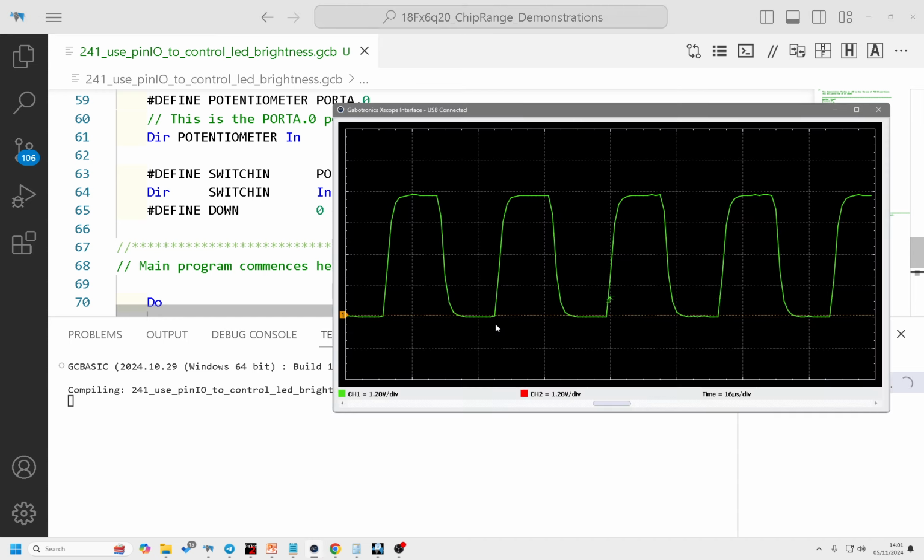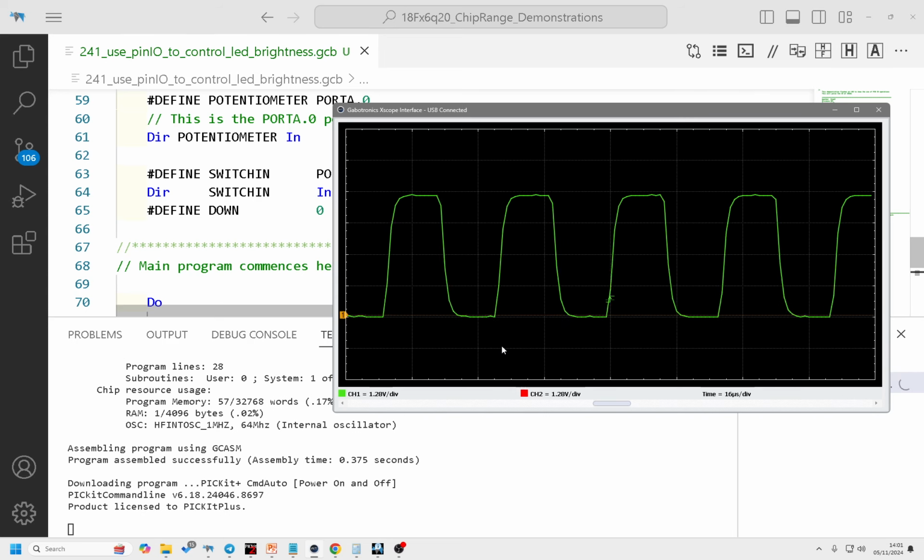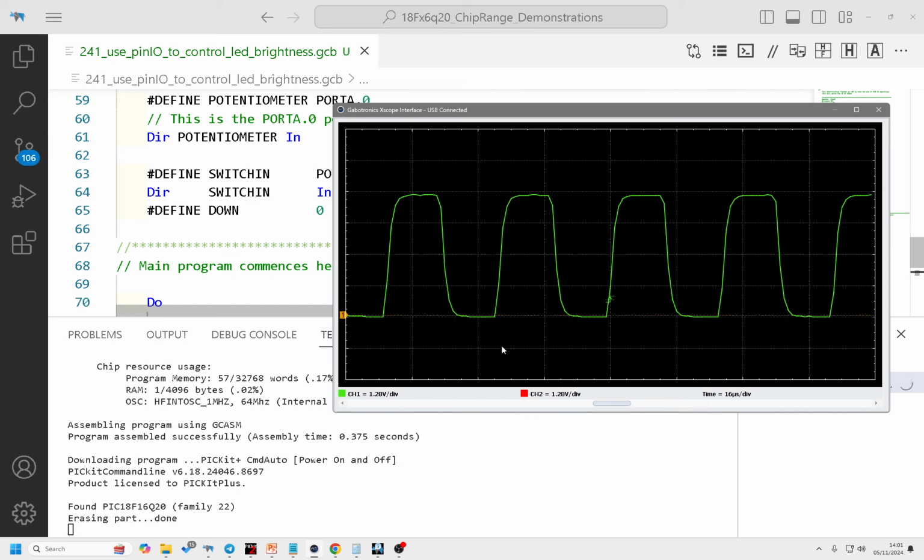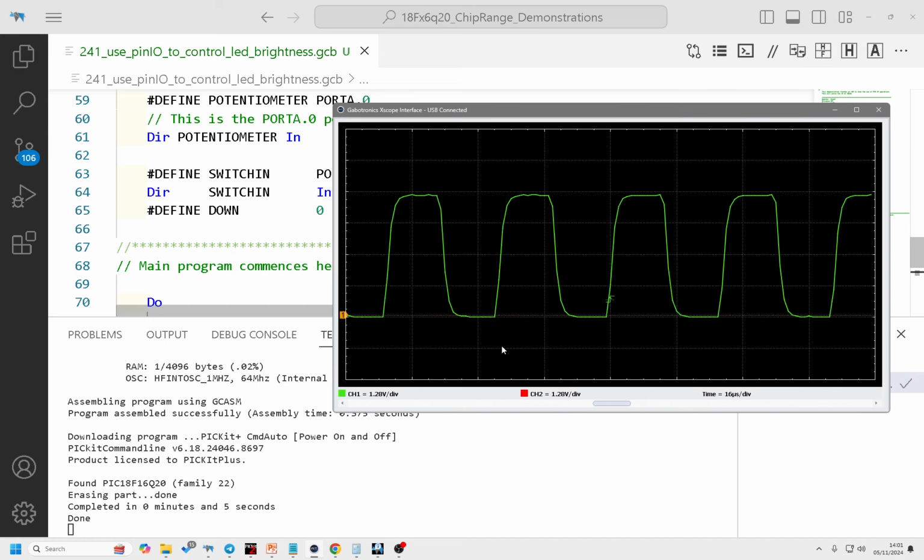So look at the scope. It's just downloading the program. It will flash it. There we go. Turned it off, and we are back to where we were. Look at that. I'm looking on the big scope. That says 38 megahertz. And look, the way that is a PWM signal, and that's at 50% duty. Well, how do I know that? I can see it on the oscilloscopes.